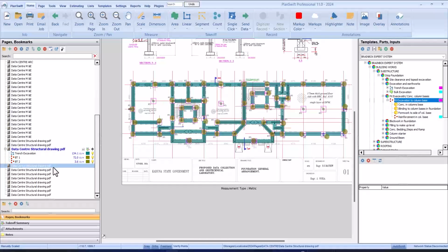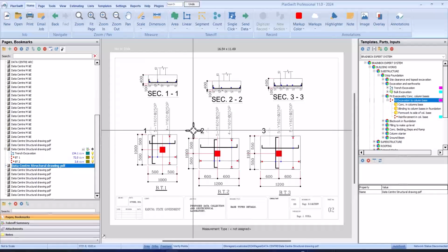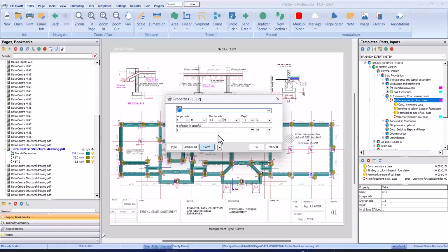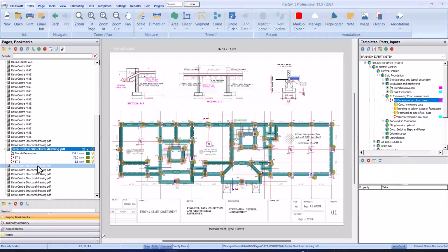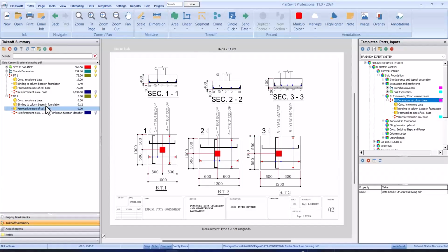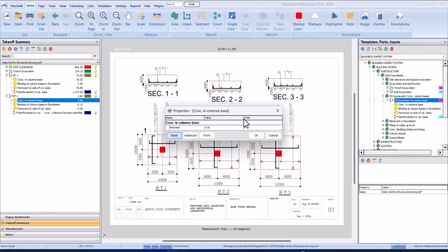And then click stop. So let's confirm the size. It is okay, 1 meter by 1.1. I think we typed the correct figure. Yes, 1 meter by 1.1. We typed the correct figure. So that's that for BT2. We'll go back to takeoff summary, make the same adjustment, 0.40.